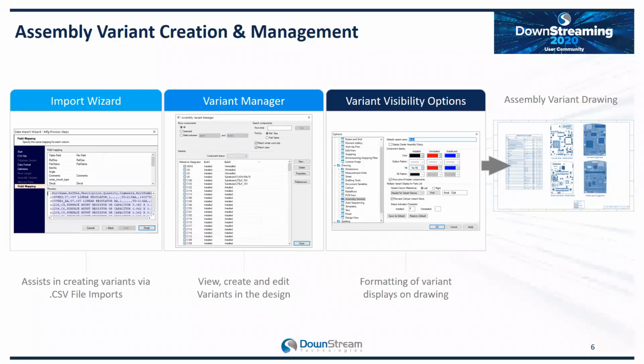We did that because that was the vehicle historically, but now that we have a flexible tool that can deal with these kinds of issues, we take the information from the schematic singularly, i.e. assembly variant by assembly variant as a CSV Excel spreadsheet, or in its entirety. Here's the whole parts list, and here's all the variants with the substituted and the uninstalled information all in there.